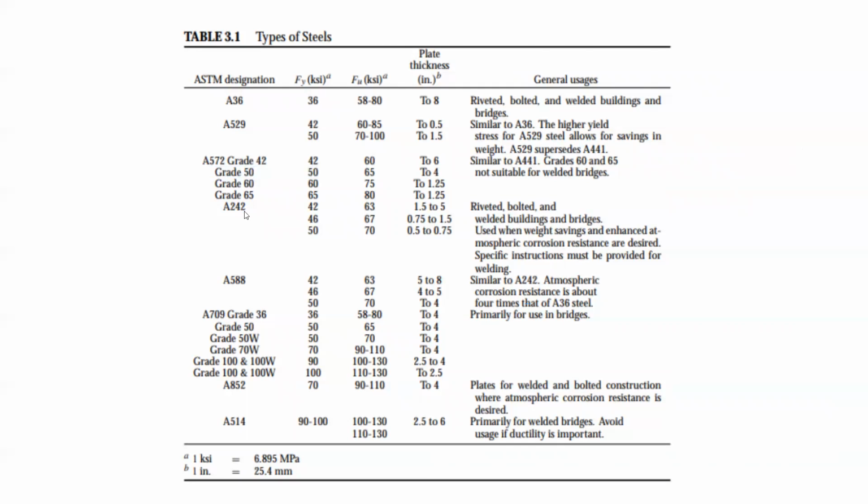Okay. And then next, pag i-convert mo naman to, let's remember na lang na 1 KSI is equivalent to 6.895 MPa para makuha natin yung megapascal. So, say kailangan mo ng A36 in megapascal. So, that would be 36 here. Yan. 36 times the multiplier of 6.895 MPa. And let's move forward.